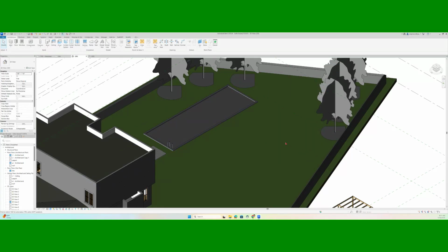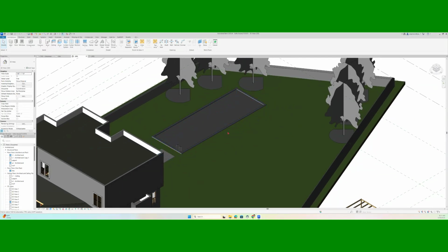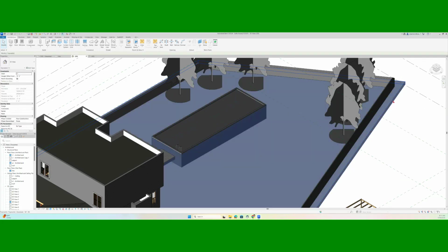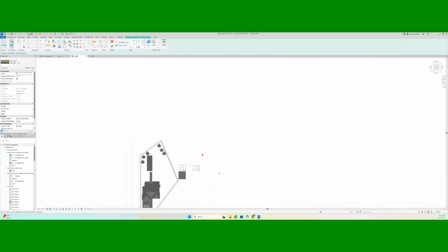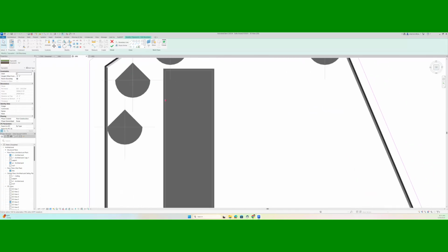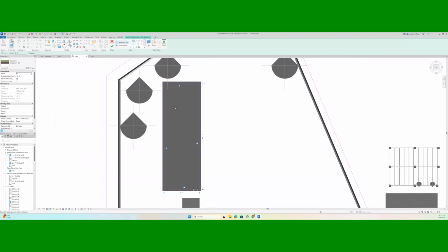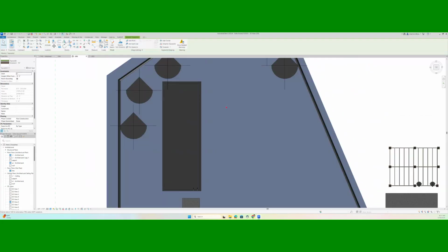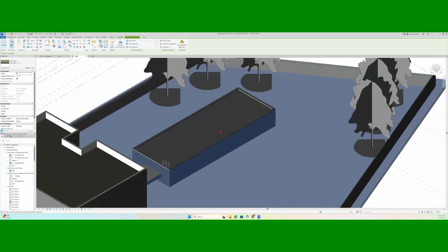But now we see that the water and the soil are competing. So there's two approaches. Let's do one that, don't do this one. Basically telling you what not to do. So select this one, edit the sketch, and on my top view, on the 3D view, I can make a rectangle from endpoint to the inside area of the pool. And I'm going to finish this. And it's going to create me a void area.